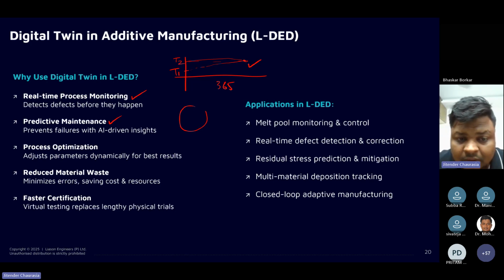It need not necessarily be torque. I can use even electrical measurements also. For the same operation, earlier my machine was taking, let's say, 20 watt hour. Now it is taking 30 watt hour, which means my system got some sort of resistance. So I should correct it. So that's how we can also call this predictive maintenance.